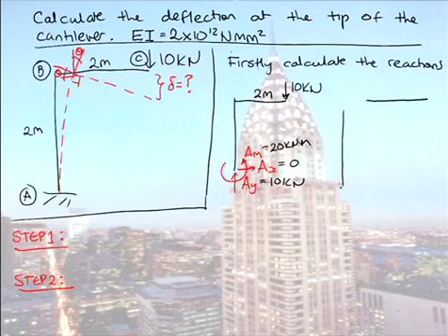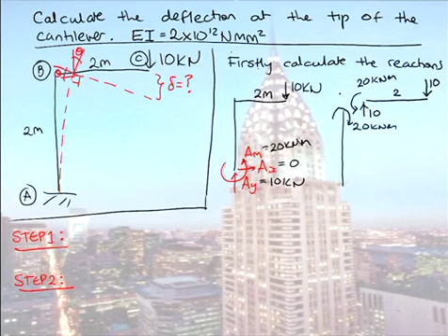So I'm going to be splitting it into an AB and a BC. So when I split it here, I have 10 down in this corner, so I must have 10 up. And that's 2 metres, so the moment there must be 20. And when you cut it on one side, if it's 20 one way, you must have the moment that's equal and opposite. 20 there. I had an up 10, I have a down 10, and that balances beautifully with my reactions. So my two free body diagrams are all balanced, all in equilibrium. Nothing is moving in space.